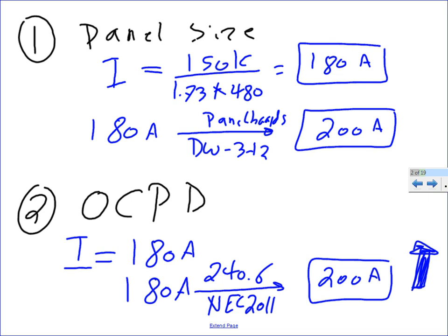Your liability is safety too. You have a load that's technically bigger than the rating. But what could happen? If I want to pull 180 amps from a 175, would I burn the panel? No. Why? Because the 175 will trip. So you can argue it's really not an issue. You're not going to burn the panel as long as you break it at 175.